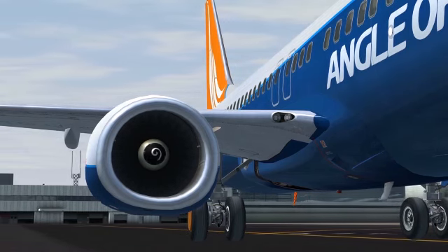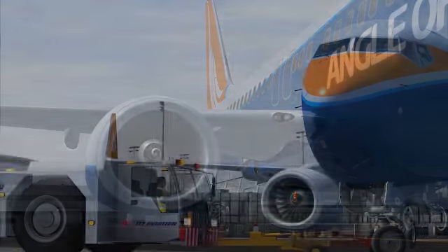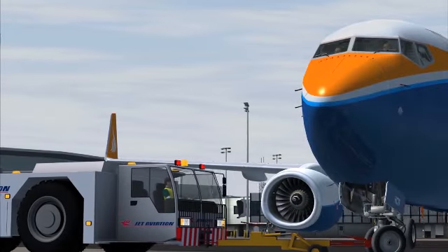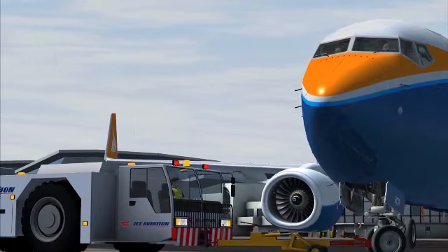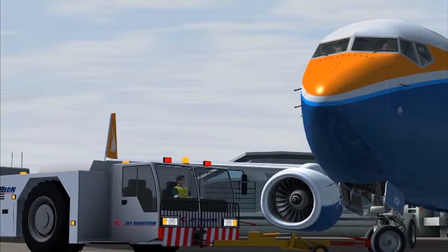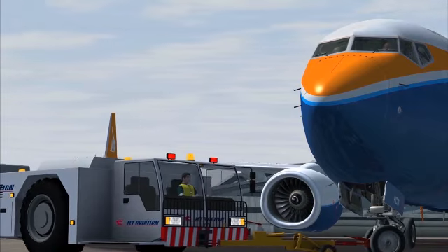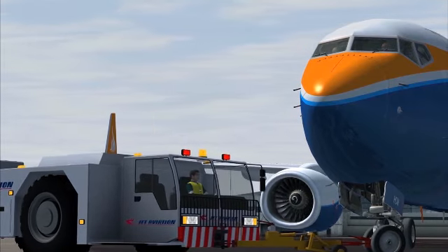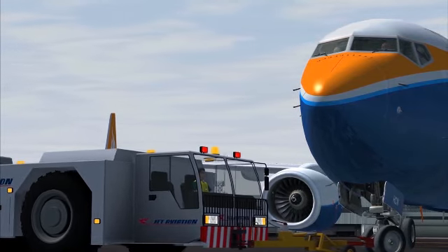The EEC has protection mechanisms where the engine start sequence is either detained or delayed when an abnormal start condition is detected. We've seen how engines are started on ground. Let's have a look at how they're started in flight in case an in-flight shutdown is imminent.